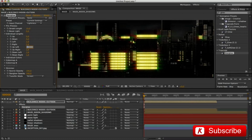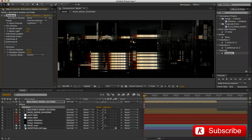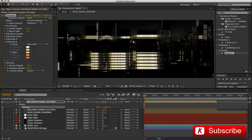Set color map A to one color, white color, and color map B to one color. On RGB value, 255, 236, 147. Source and Star Glow opacity to 60. Set the mode to lighten.